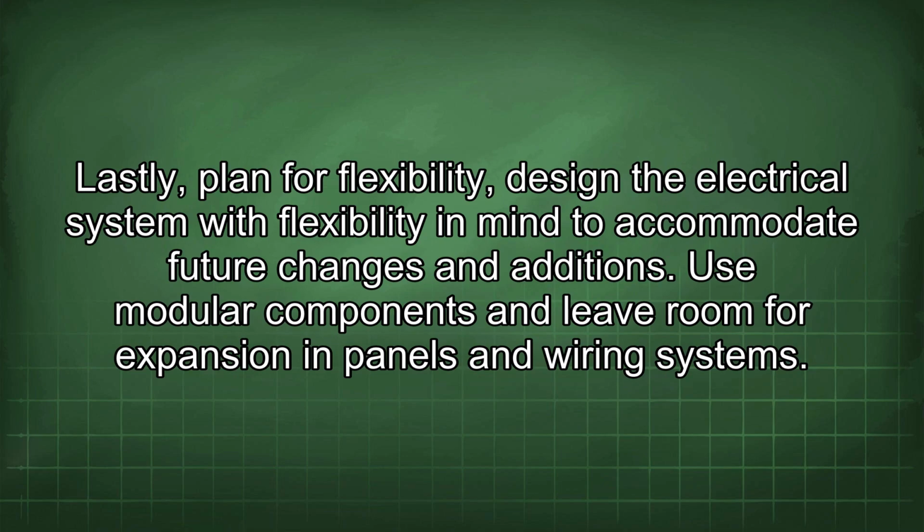Lastly, plan for flexibility. Design the electrical system with flexibility in mind to accommodate future changes and additions. Use modular components and leave room for expansion in panels and wiring systems.